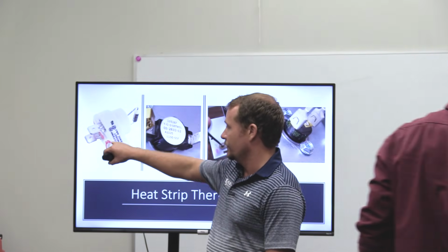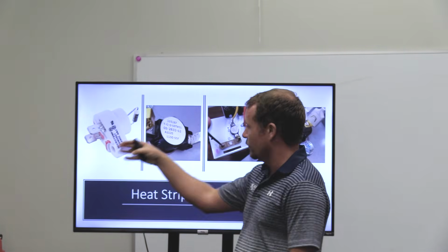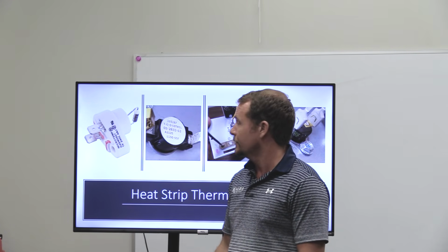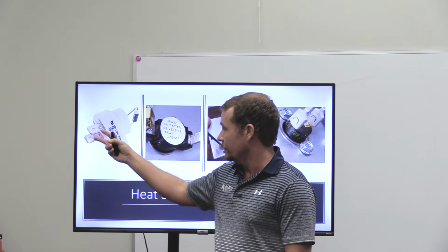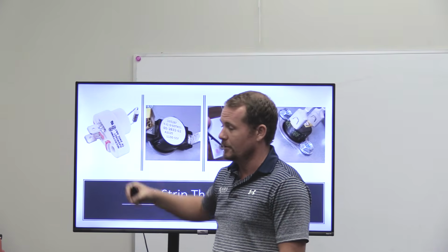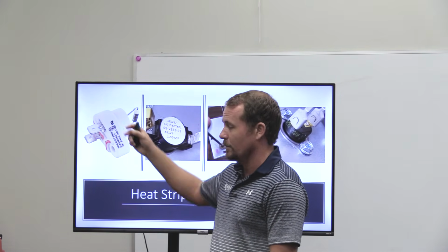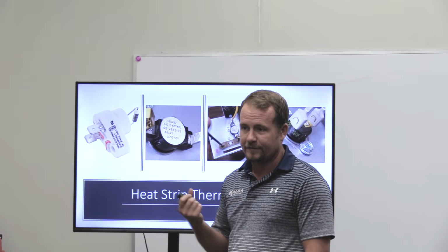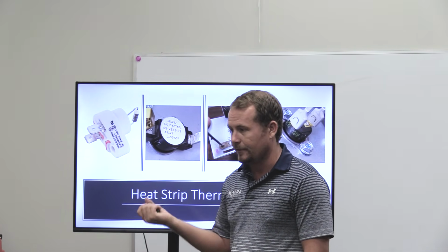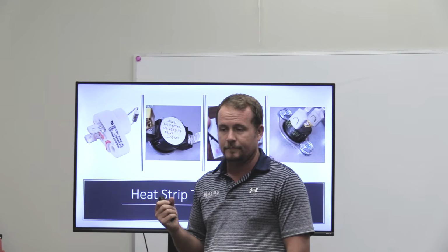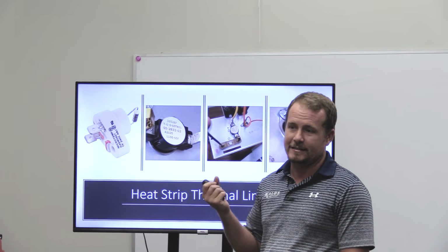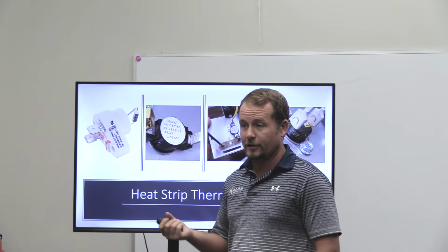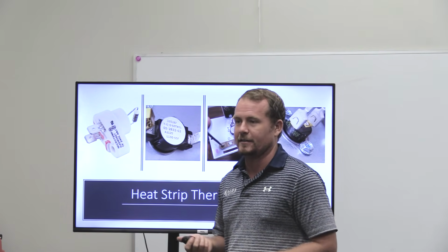Now, how would you know if one of these is open? Or any of these? Ohm it out would be the easiest way, right? So you take the wires off, take your ohm meter, obviously shut the power off first, measure across it. What are you going to measure if it's open? OL, infinite ohms. No path, right? If it's closed, maybe if your meter has that setting on it. But a lot of times I see techs don't have their meter on there, like it's not ringing out. You look down at the meter and it's reading 0, right?